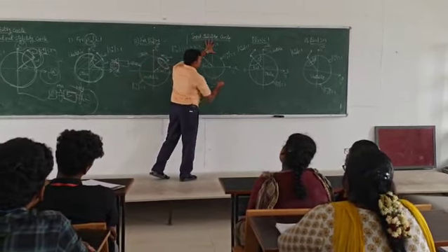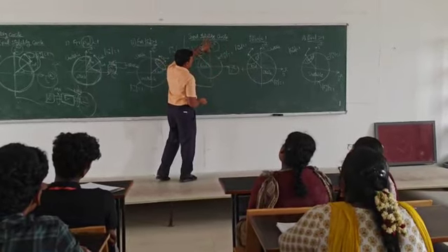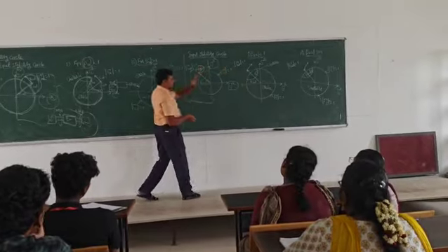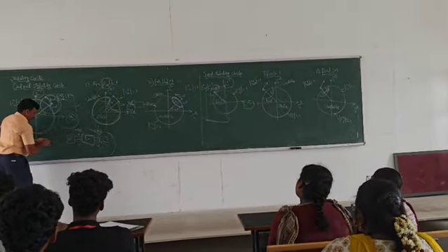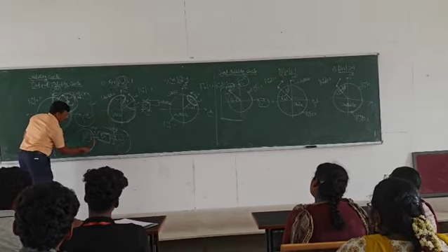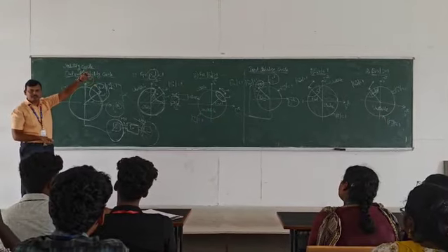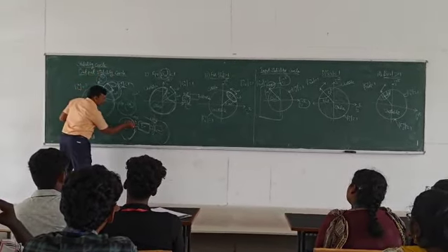Here the x-axis and y-axis represent the source reflection coefficient, resistance and reactance. We take the source in this portion, because we are now concentrating on the input stability circle, so we focus only on the source.